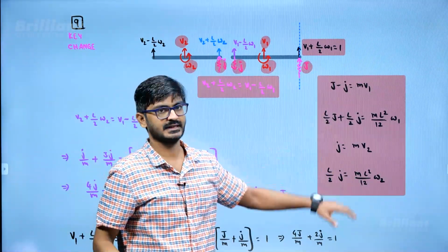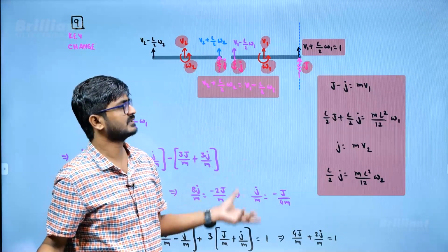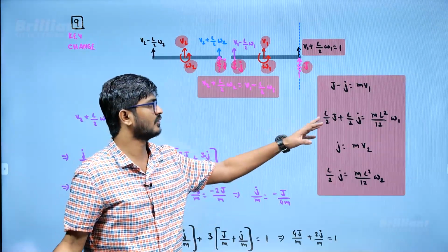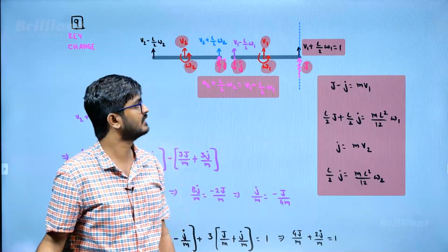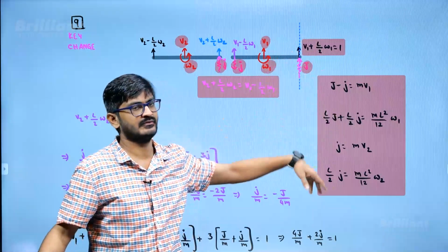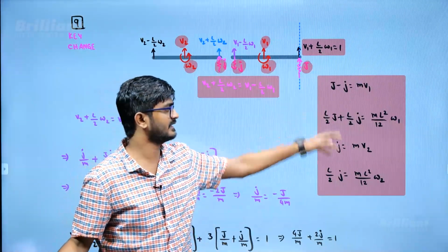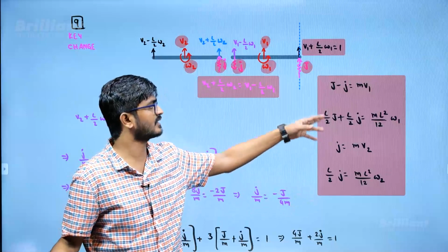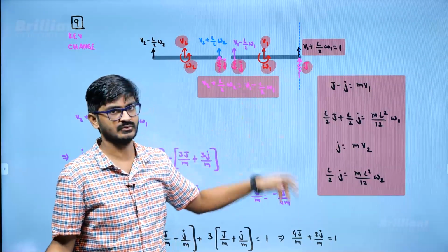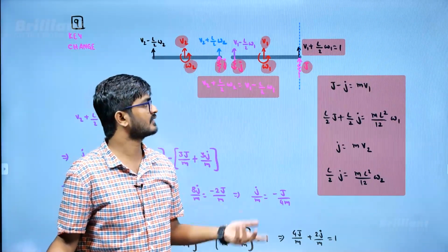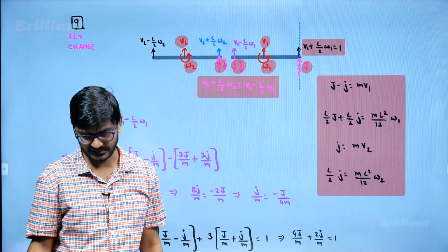So, these are the equations I have written because the number of variables looks more for me. So, I had to go with this instead of conservation of angular momentum about this point. When I do that, I will be getting only one equation, but when I write it this way, I will be getting 4 equations, though the number of unknowns I am bringing are 2 extra. Though I am bringing 2 more unknowns, I am getting 4 equations, so that is much better, right?